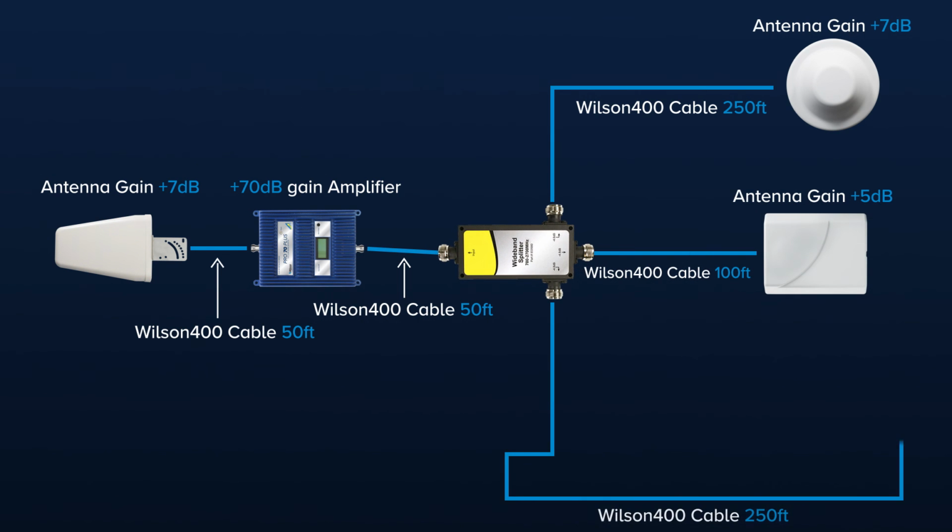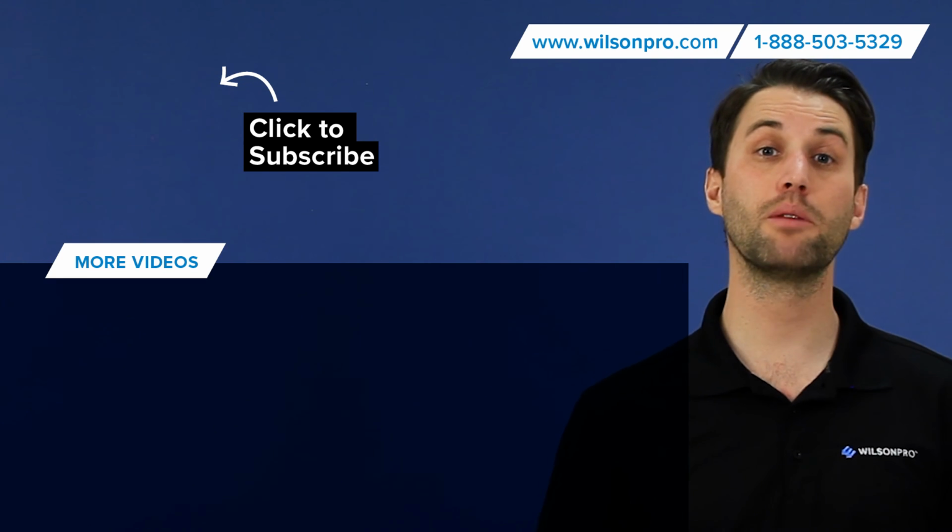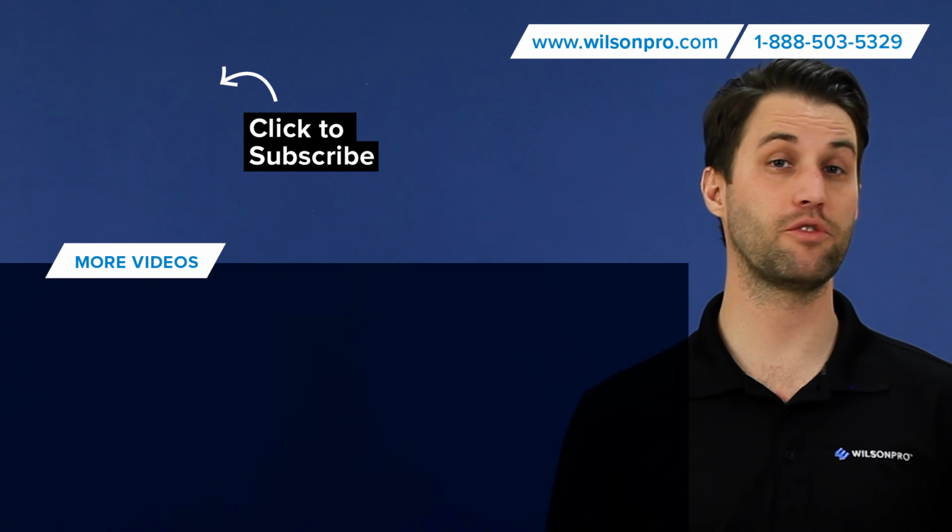If you're using a splitter to branch out to multiple broadcast antennas, everything will be the same up to the splitter. Then you'll just need to calculate the losses and gains individually based on the cable lengths and antennas that you choose for each run. I hope this has helped you understand how to calculate coverage area for a building.